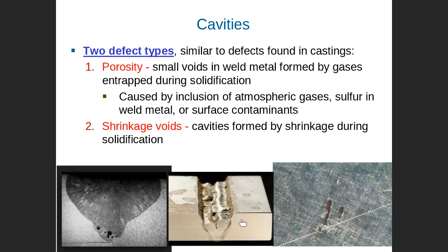Liquid means the two base materials must be melted. This one must be liquid in the welding zone, not everywhere. You're not going to melt all the part. We're going to melt only here in the welding zone. Then you get liquid, and you get liquid mix, and then probably added filler.